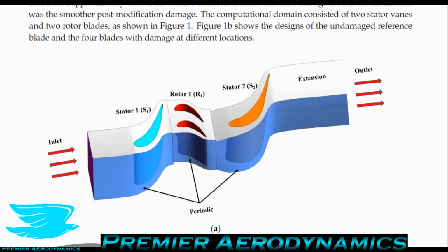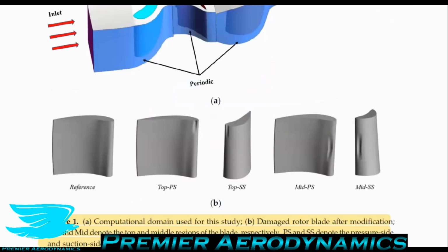So if you look at the wake coming out of a turbojet, you can actually tell whether it's underexpanded, overexpanded, or perfectly expanded just by looking at the wake. If it dramatically increases in size, then it's underexpanded. If it shrinks, then it's overexpanded because the pressure coming out is less than the outside pressure, and the outside pressure then compresses that wake. If it stays constant, then it's perfectly expanded, and that means that you've done your job properly with the turbine and the entire turbojet in this case.